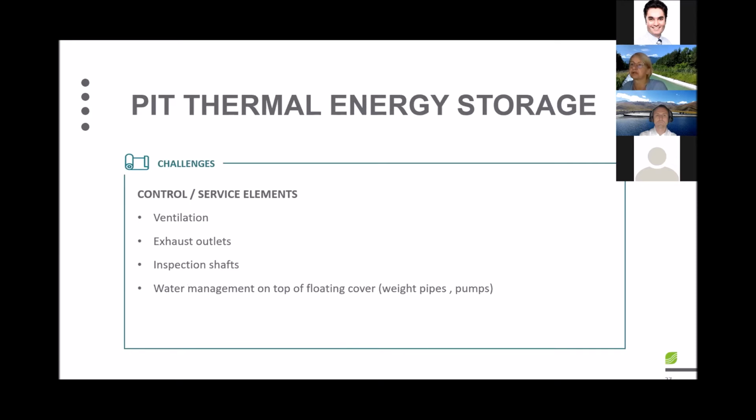So which control and service elements are used on such a floating cover? Yes, we have the ventilation layer, ventilation buildings to keep the insulation dry, and we have to address exhaust outlets to get rid of the oxygen which is accumulating below the floating covers.